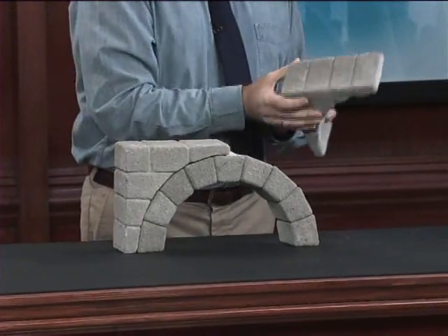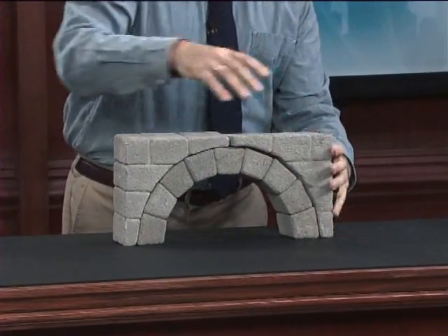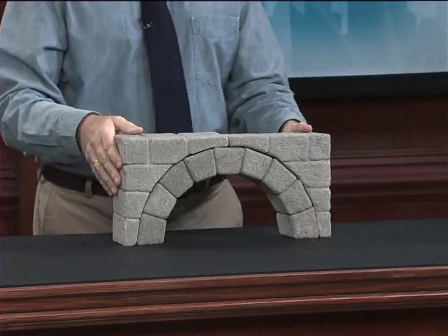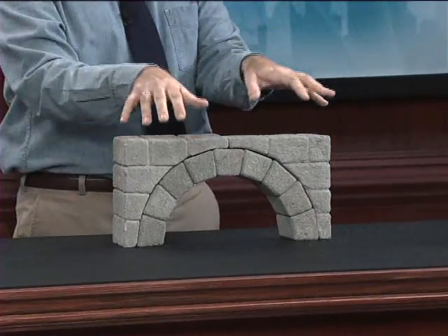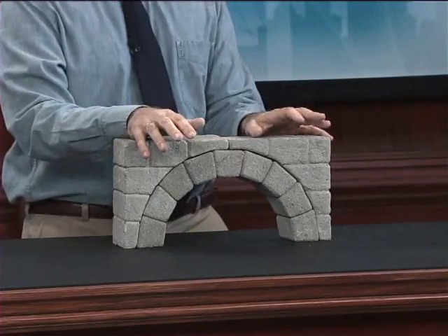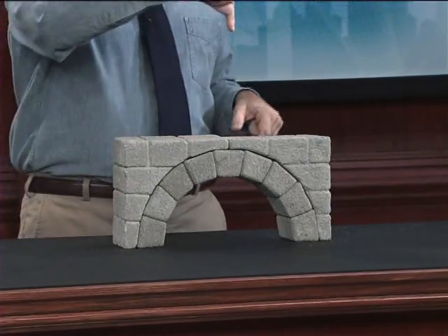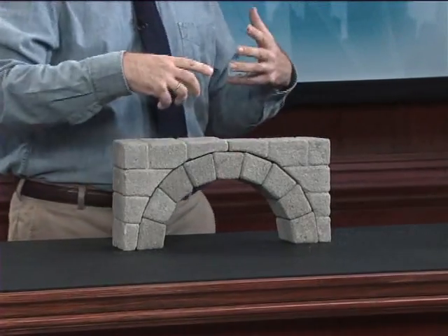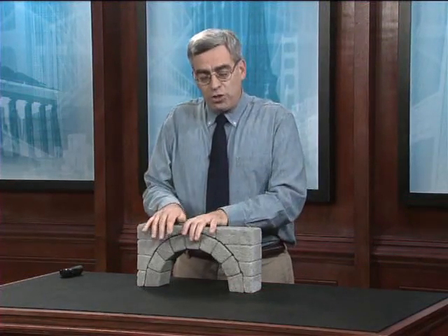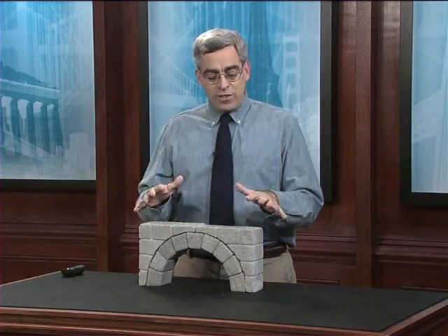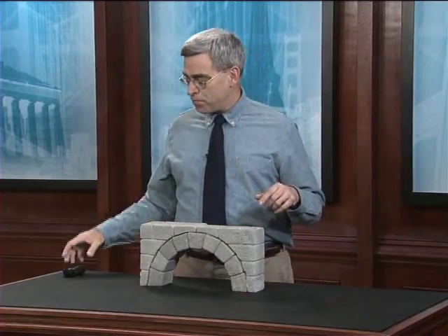been rebuilt for us. And you can very clearly see that at this point, that failure mode, which consisted of the outer ends of the arch bulging up and outward in response to the concentrated load in the center, is virtually impossible now. The spandrel preserves the shape of the arch so that when we press down, that bulging can't occur. And, by the way, the spandrels also have considerably more weight out here near the ends of the span where that additional stability is needed to keep the bulging from occurring.